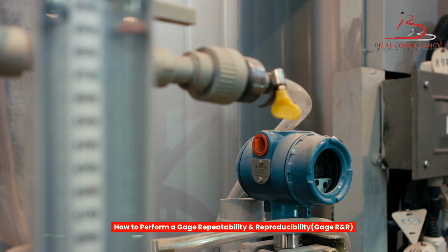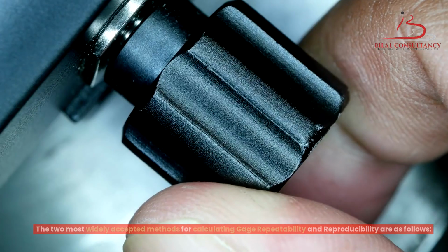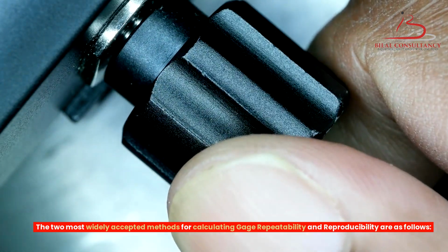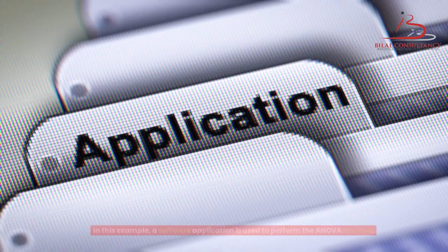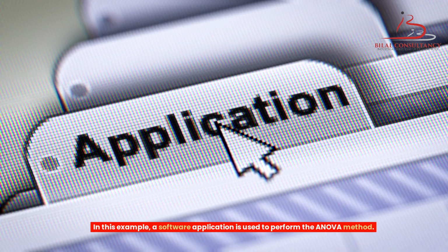How to perform a gauge repeatability and reproducibility, GageRnR. There are several techniques for completing a GageRnR study. The two most widely accepted methods for calculating gauge repeatability and reproducibility are as follows. The average and range method. The ANOVA, analysis of variance, method. In this example, a software application is used to perform the ANOVA method.